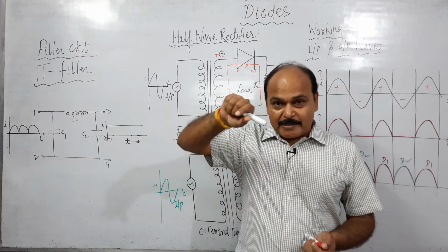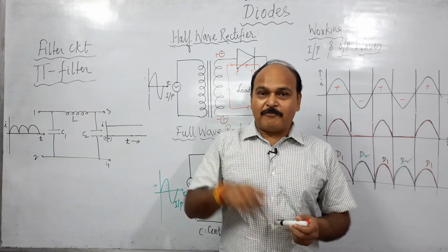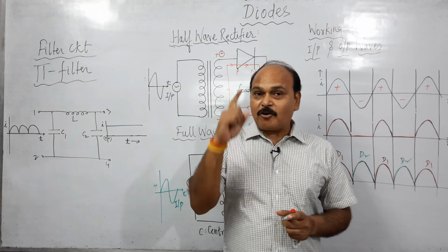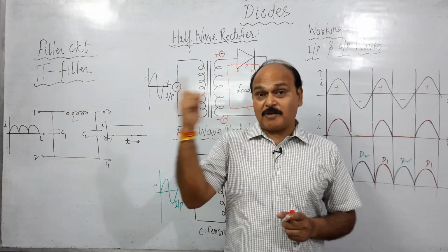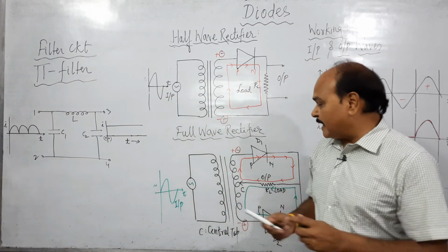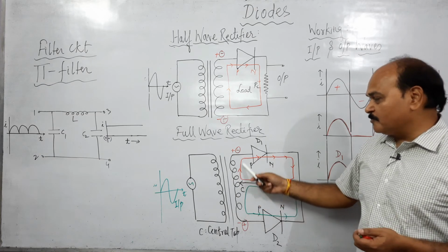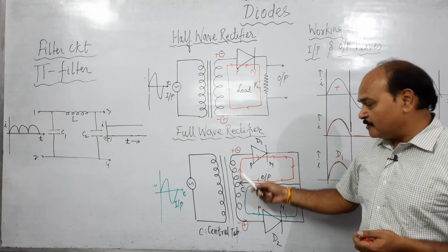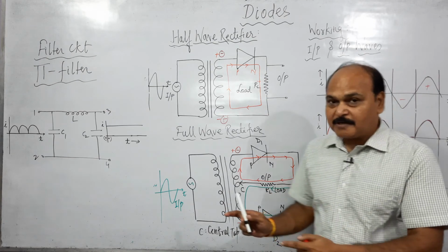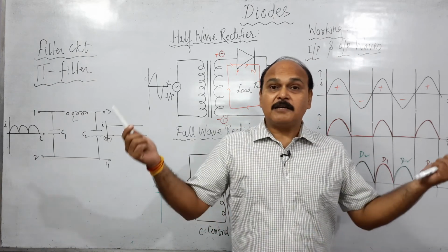Well, in the eliminator there is a knob, and with the help of that knob we can vary the output voltage we obtain, and that knob indicates voltage from 1.5 to 12 volt. That variable knob is nothing but the central tap of the full wave rectifier. This central tap moves from one end of the secondary coil to the other end, and in the process the output voltage we obtain varies from 1.5 volt to say 12 volt.